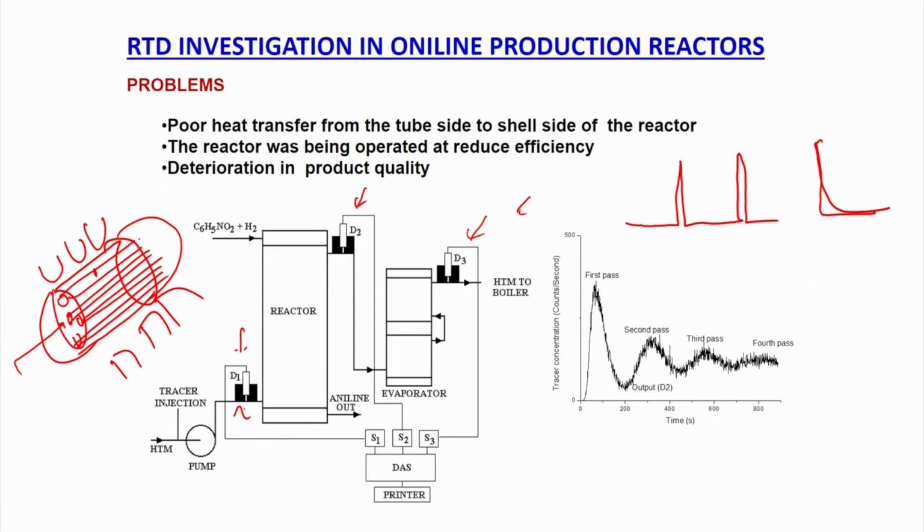While if there is a leak, what will happen? The tracer will start coming out from this place and it will spread. So, what you will get? You will not see the radiation reducing, but at a certain location you will see that it is now spilling outside and your count on the detector will increase. Again, Beer-Lambert's law, because now the distance is reduced. So, you can pinpoint where the leak is taking place and you can replace that tube. That is the benefit of these techniques, which are widely used in the industry to analyze reactor performance without disturbing the flow, through radio tracer RTD experiments.